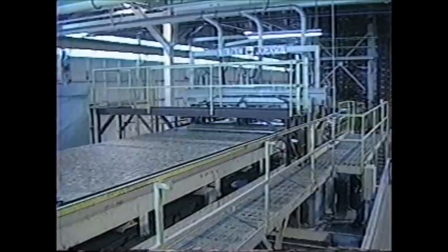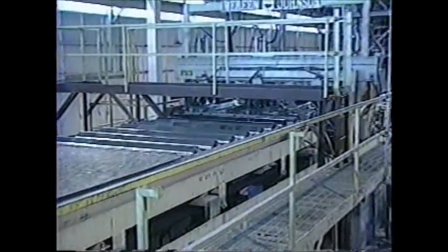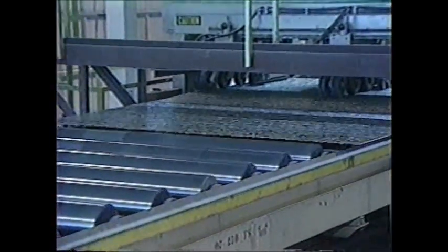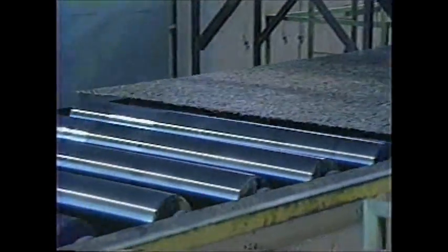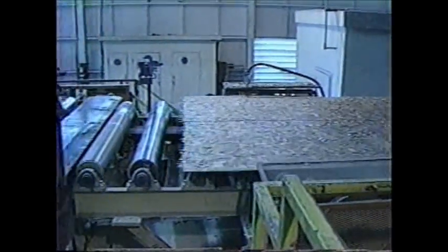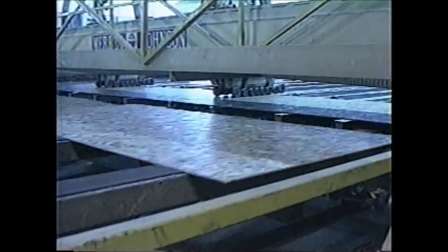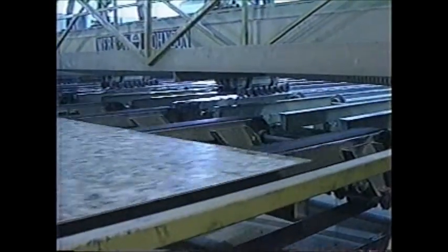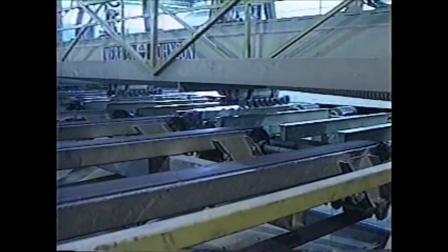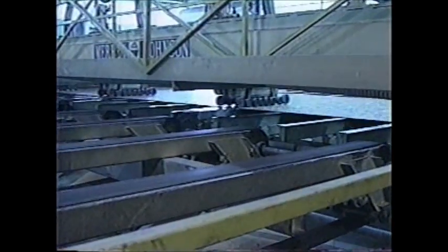The first set of saws cuts the 100-inch panel in half and trims the edges to produce 2 4-foot by 24-foot strips. The panels then make a left turn and are routed through a second set of saws which cut each 24-foot strip into 3 8-foot panels, producing 6 4x8 panels from the original panel.